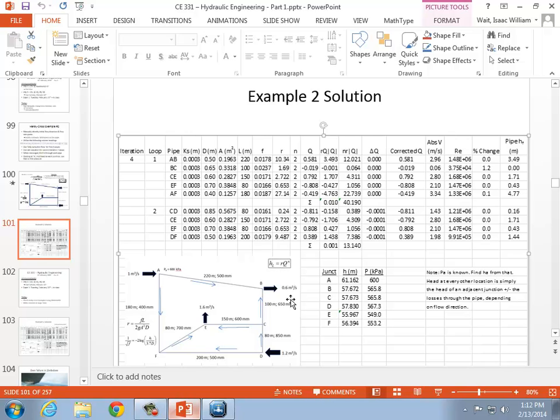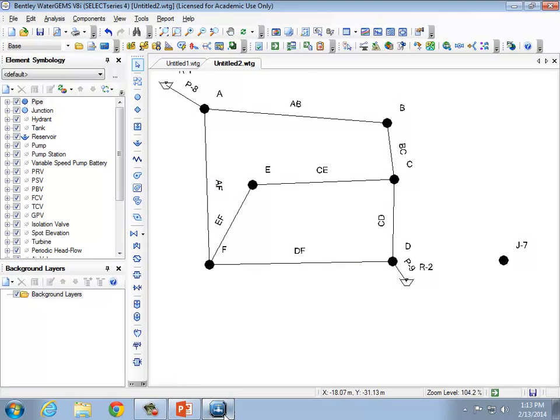All right. And then in this check of the solution that we're doing using WaterGEMS, we know the pressure at A and D is due to some water flowing in. And so that's why I had to put reservoirs in both of those locations, because that's where the water is going to come in from in this model. Just making sure we haven't done water going out yet, right? No, we actually did. Let me remind you where that was at.